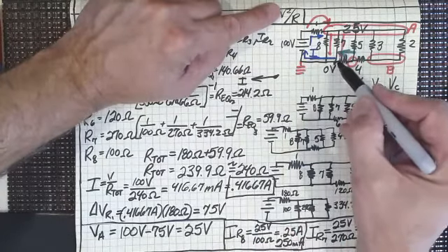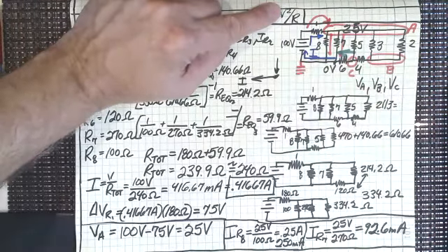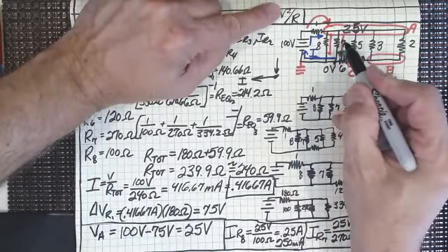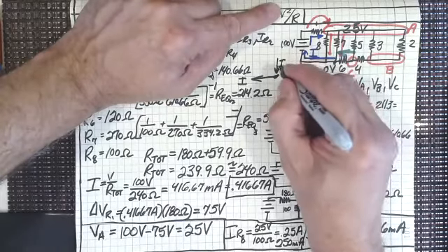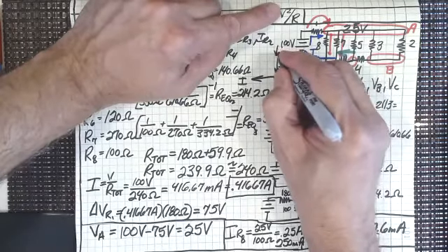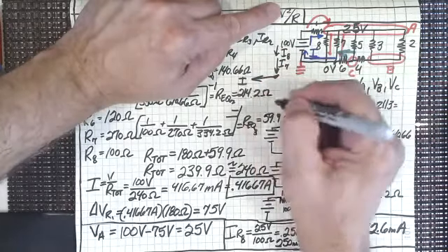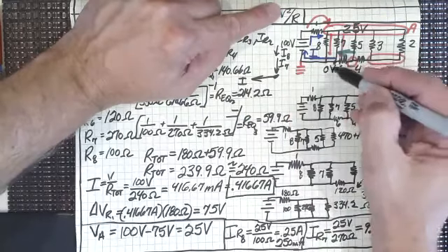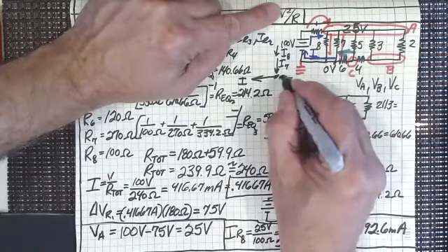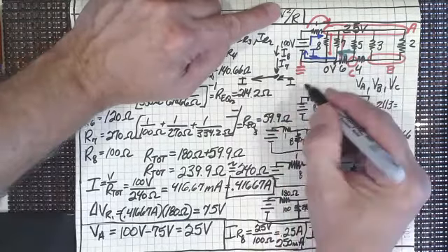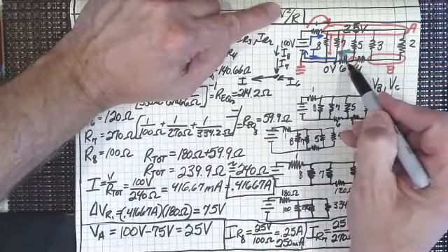What's going into the node? Well, this is going into the node. Both of those, the current from 7 and the current from 8. So I'm going to put both of those. I7 and I8 are both going into that node. I is coming out, but I7 and I8 are both going into this node. The only other thing going into this node is what's coming out of the rest of the circuit. I call it I6, right? Because it's flowing through resistor 6.